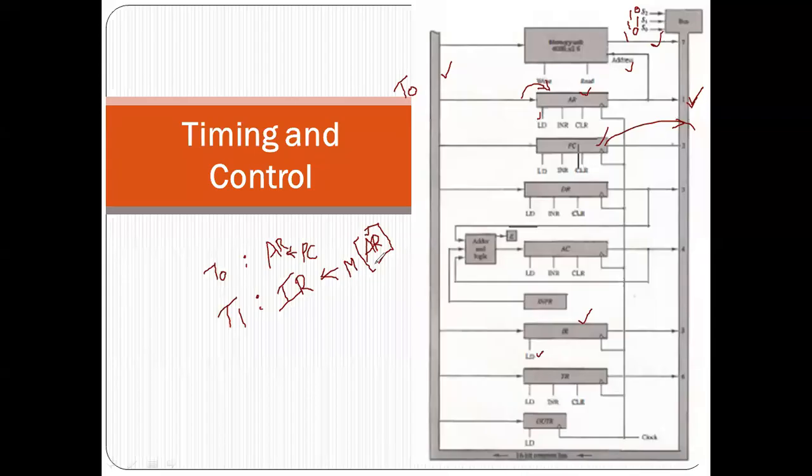After this we have finished the fetch operation, right? This is what is called a fetch operation. Fetching is nothing but reading an instruction code and placing it into the instruction register. With this, the fetch operation is finished. At the time of the fetch itself, one more micro-operation is finished, that is, incrementing the contents of PC by 1.